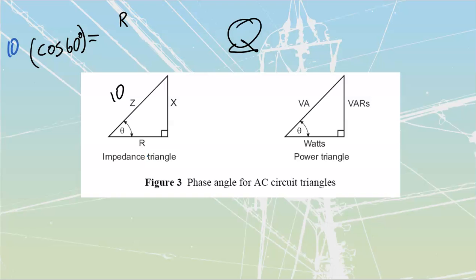But let's deal with this one in its simple form over here. They say, what's the phase angle for a circuit that has 250 VARs of reactive power? So we know we're working with 250 VARs and 800 watts of true power over here. I could use Pythagoras to figure out a VA from this, but I don't need to figure out that VA for this one.